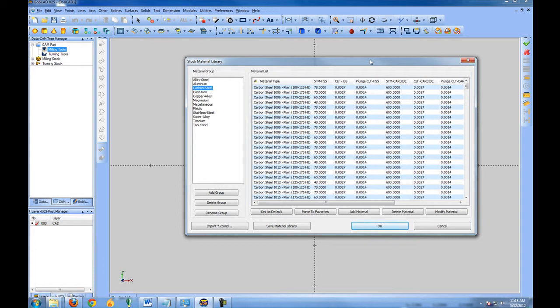What you will find, though, is there can be a lot of variation on what's needed for feed rates based off of your tooling and the material that you're cutting, and also the rigidity of your machine and maximum spindle speed settings. So these settings are a very good start, however, may need to be customized for your needs. It's very important that when running a program, and especially for the first time, that you look at the feeds and speeds being used and decide whether or not they're good for your tooling setup.